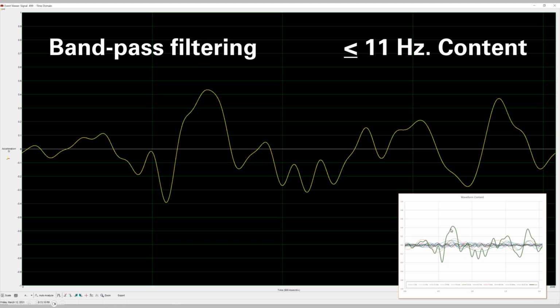Well, look at, here's what I actually did in Excel. They did these completely opposite. I exported all those signals, I added them together, got this green trace, and if you look here, it's exactly the same. It's exactly the same trace. So the point there is there's a method to the madness of how the waveforms can basically be dissected to understand more about very specific frequency content.